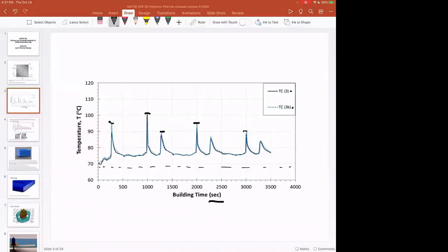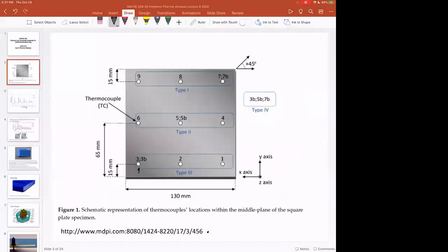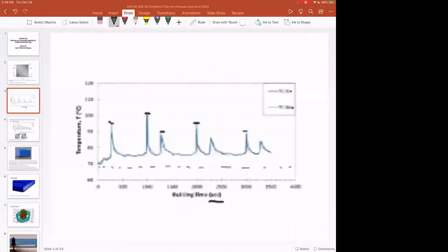course of an hour. And so a lot of you have some background in engineering, and you know, as you thermally cycle a part, you can get stresses built into the part from this thermal cycling, and also thermal cycling of one location in this plate that increases the volume of that material due to the coefficient of thermal expansion. And so you can get built-in stress by heating up one part of the plate and not the others. So this is really cool.